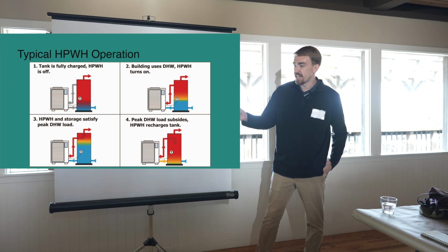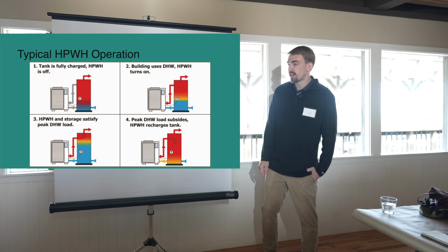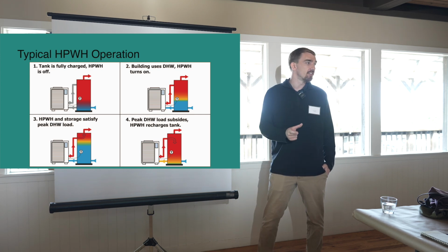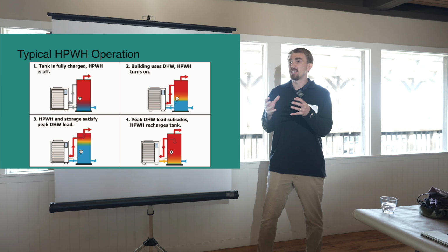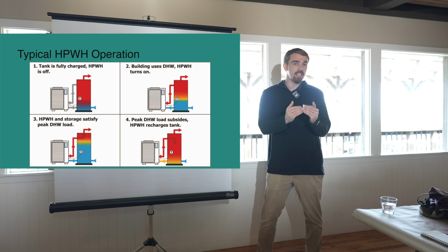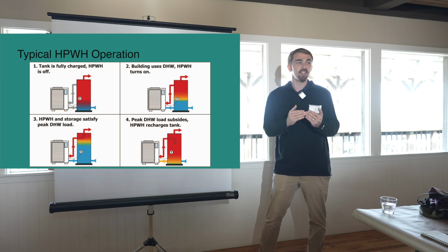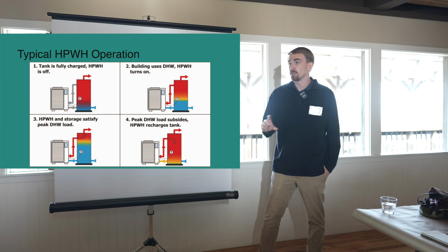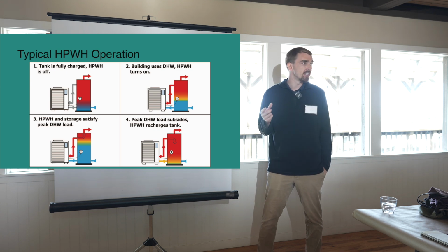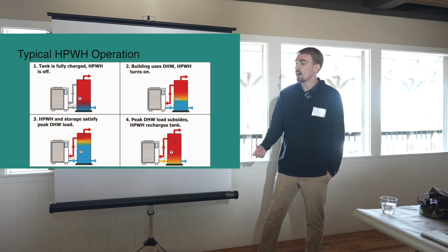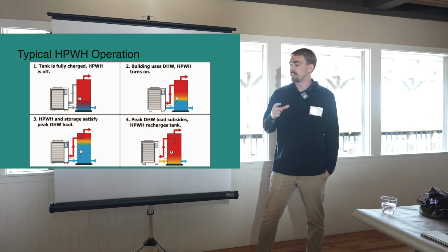And your tank can drain down almost completely when it's stratified storage. So we're getting a lot of energy out of this tank. We're not mixing the tank up and making it unusable by the time it's down to 115 degrees. Most of the tanks can be down at cold water temperature, 60, 70 degrees depending where you are. So we're getting a lot of BTUs out of this tank with the stratified storage.